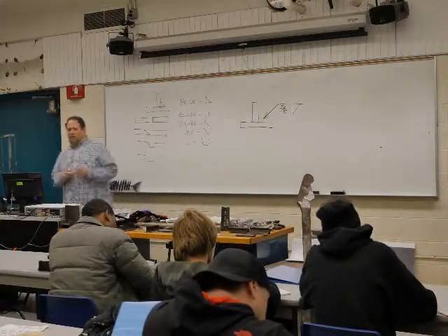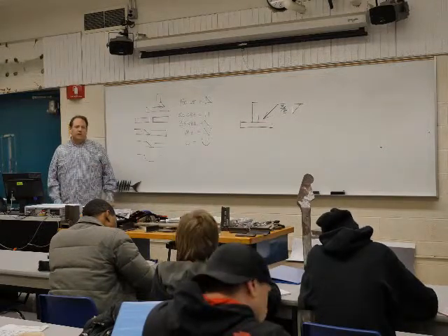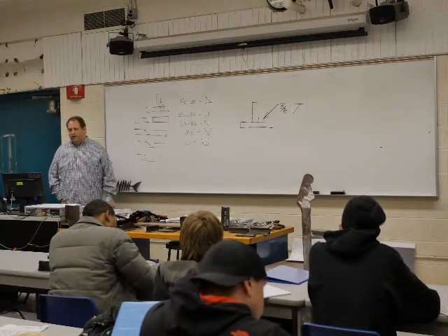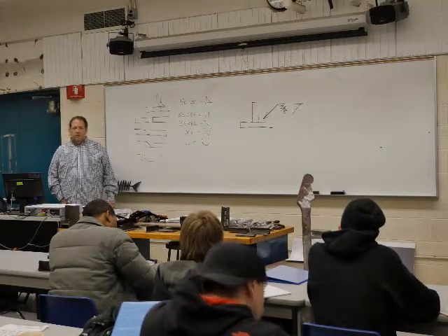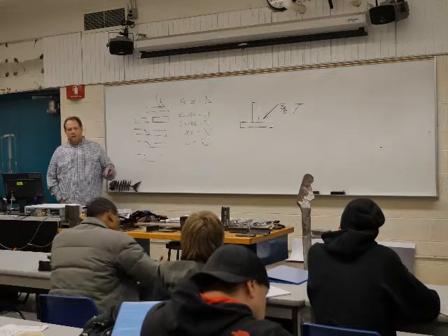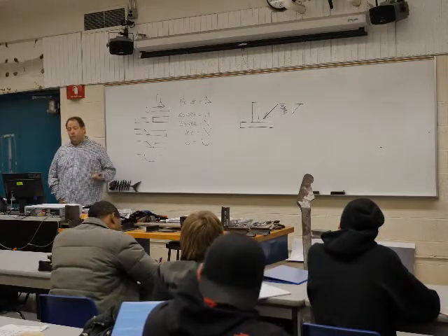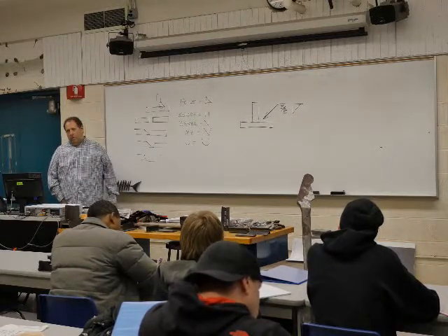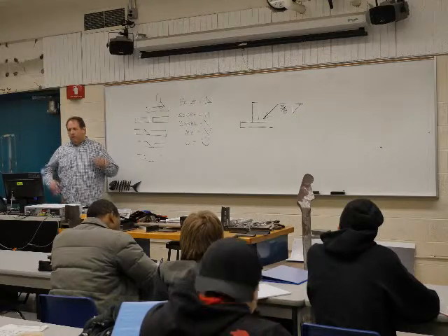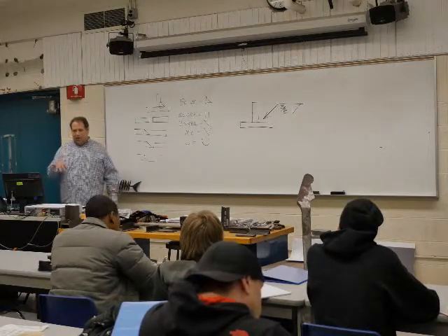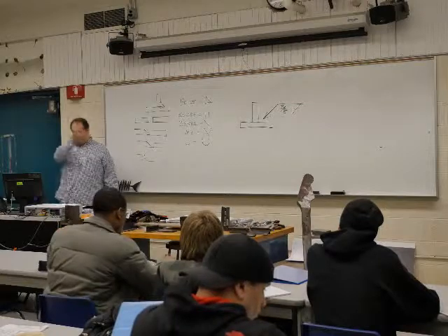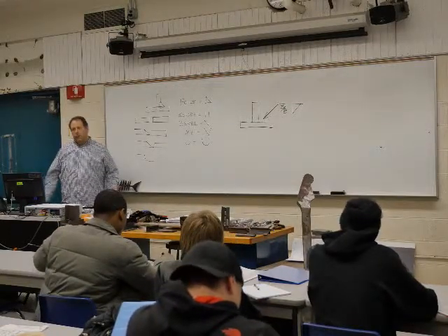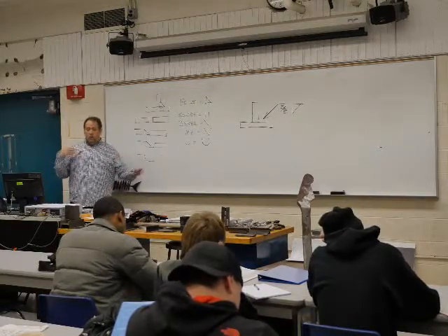Okay, so 3/8, and what is that? 3/8 of an inch, 3/8 of a foot? Generally, it's 3/8 of an inch. If you've seen it in a fraction form, it's inches. You could come across it in metric. Maybe they say 4. Well, a weld shouldn't be 4 foot long, so we can assume right away that it's metric, but somewhere on that print, it'll say whether it's standard or metric. So just make sure you understand that you could get either one.